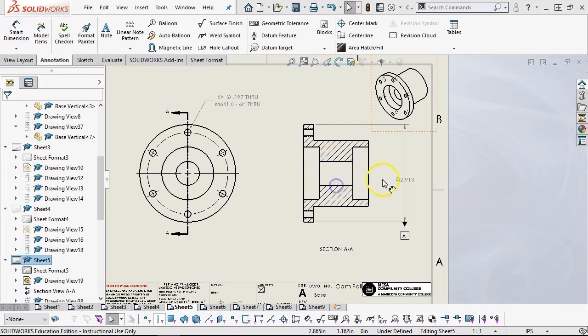All right, so the not critical dimension here then would be the 709. It's just acting as the clearance for the shaft. And so I want it to be fairly close, but it has enough clearance. I don't want to drill it any larger than I have to.